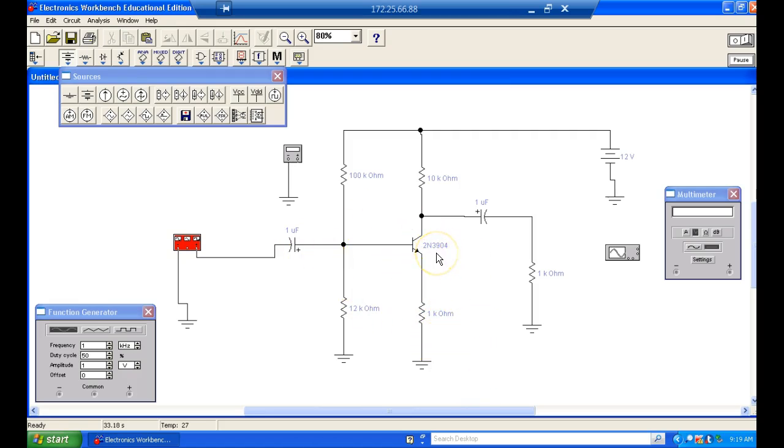It looked like our typical beta worked out really good, guys. And now 3904 typical beta is around 100 for this transistor that we'll be doing. Are we okay? Okay, so what's going to go on here, guys, if I start doing stuff? What are some of the things that could go wrong with this guy?